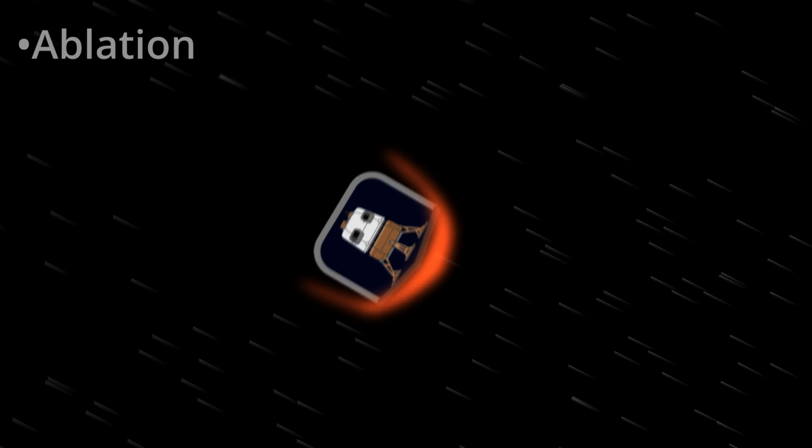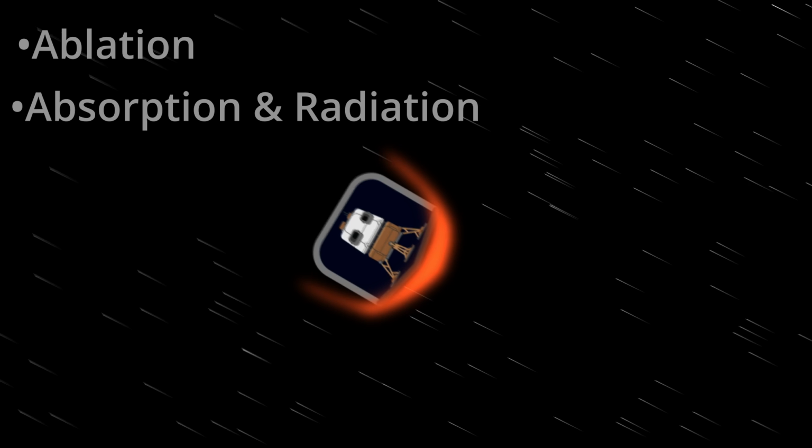Even though the temperature is raised up to 1300 Celsius, if the heat shield didn't have a way of removing this heat, its temperature would be rising, putting the payload behind it in danger. There are two basic ways that a heat shield can remove heat. One is through ablation, and the other is through absorption and radiation.